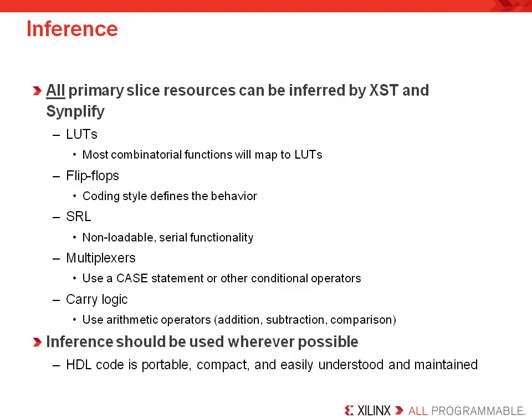All primary slice resources can be inferred by XST and Simplify. This includes LUTs, flip-flops, shift register LUTs, muxes, and carry logic. However, you must be sure to code for the resources properly. This means that if you define a flip-flop with an incompatible combination of control signals, you'll get something slightly different, probably with the LUT input used for a control signal.